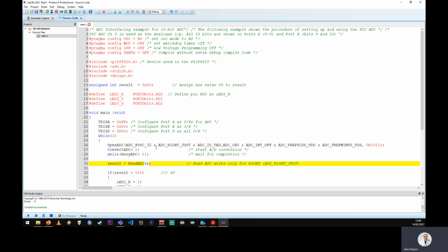The difference between this and the previous way that we did examples was that in the previous method, we didn't actually save the ADC result. We just overwrote it every time we converted. By sending it into a variable now, we actually have a local copy. And as long as we don't manipulate that variable, it will contain the current result of the ADC.